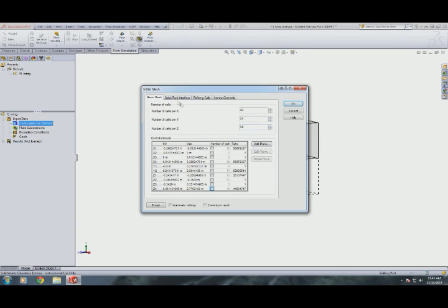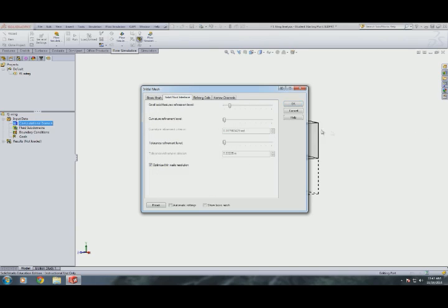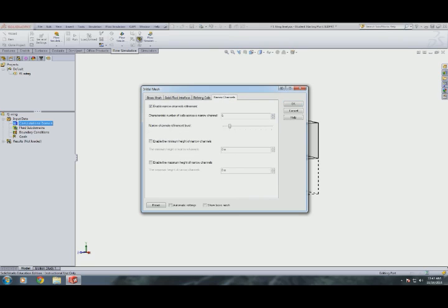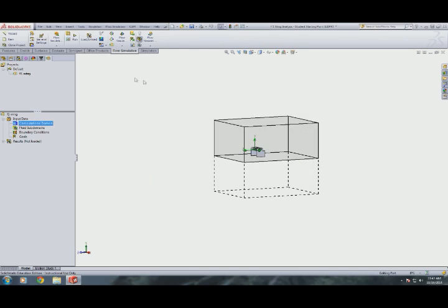Solid fluid interface, small solid refinement level 4, or yeah, it's actually going to be 3, this one gets ticked up to 2. Refining cells, we had none of that, and narrow channel refinement is enabled at level 5. Okay, so that's the mesh setting, and I suppose that's it. We just run it.